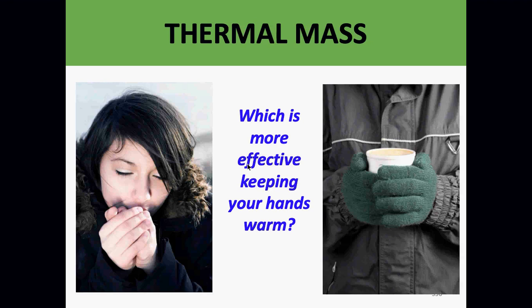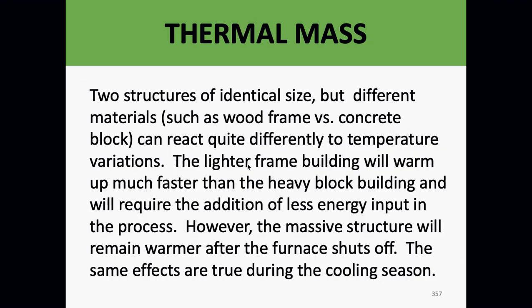Thermal mass. Two structures of identical size but different materials can react differently to temperature variation. A wood frame building will warm up much faster than a heavy block building and will require the addition of less energy in the process. However, the stone block building will remain warmer after the furnace shuts off.